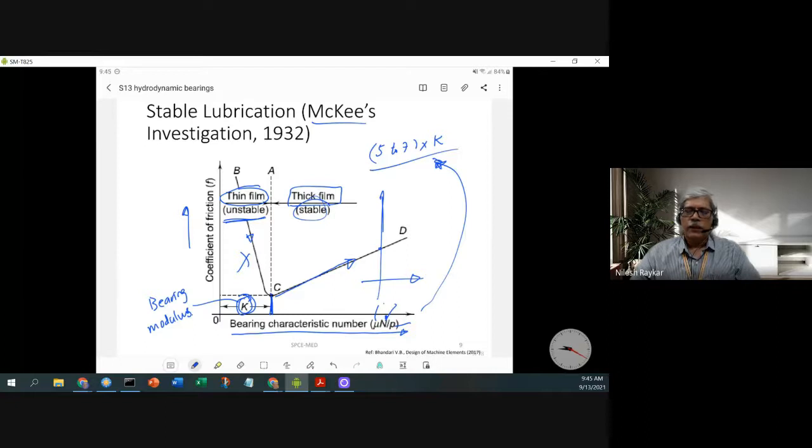If you are having high fluctuations in the load and more impact conditions, say you are using this bearing in some tool which is having intermittent impact, such as a crushing operation or braking operation, then you need to use higher values.